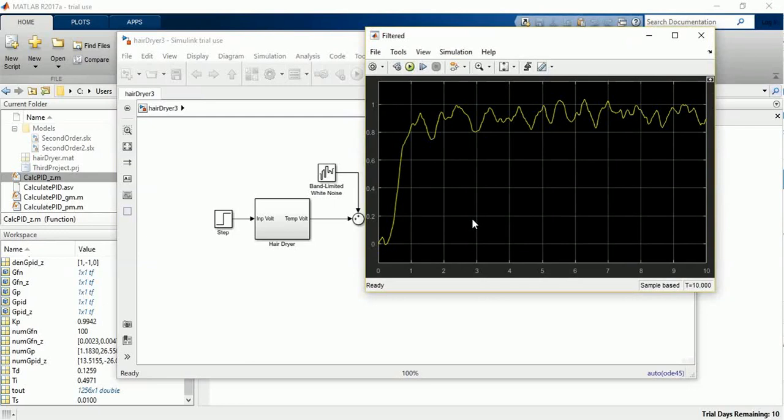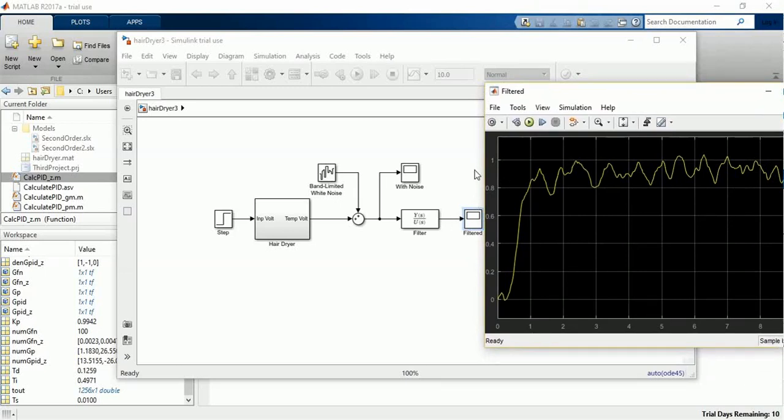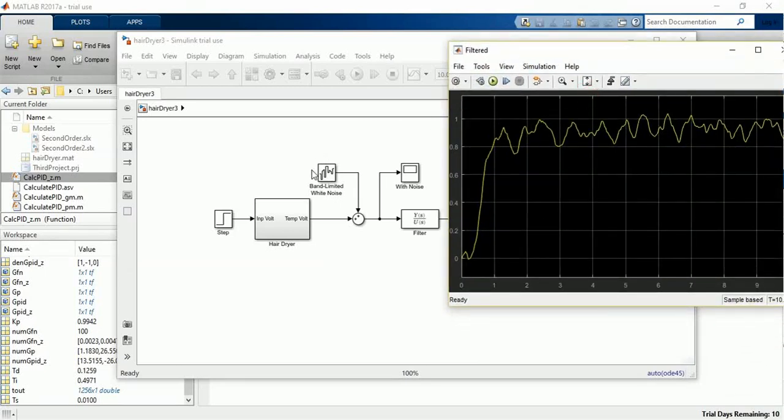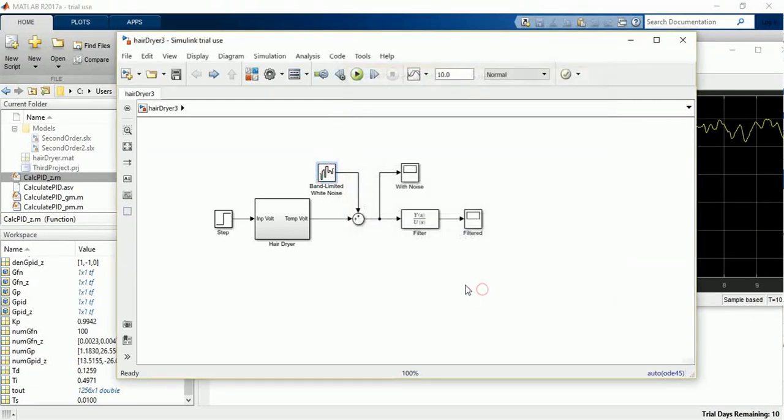As you can see, the output is smoother, it's still having variations, but that will be okay. And this is the output we are going to use to do the feedback. So the error will be the set point minus this signal. This will be our output, and directly to the PID controller. As you can see, we have changed the system. If we compare this with the previous...